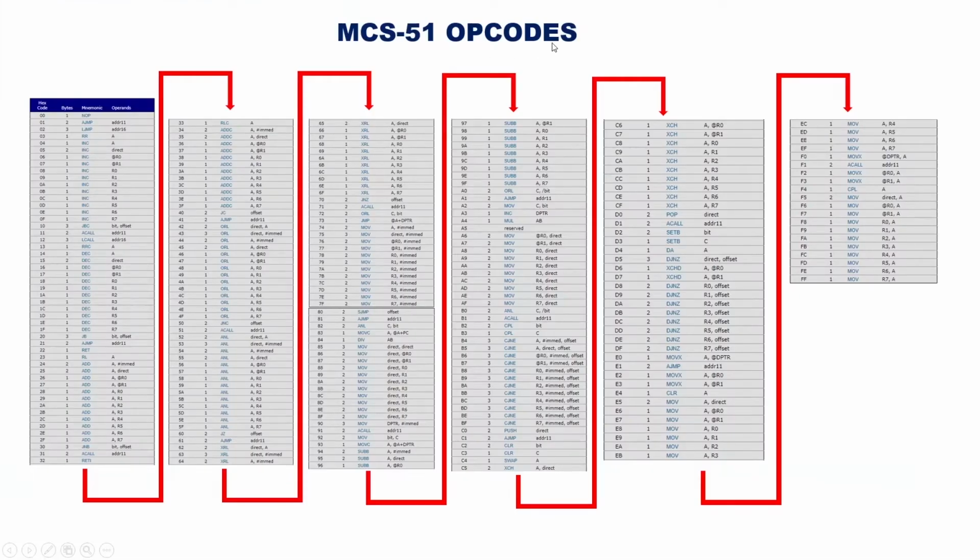In the MCS 51 of course we can find the instructions MOVX A,@R0 and MOVX A,@R1. Both of these instructions, MOVX A,@R0 and MOVX A,@R1, are used to move data externally when we use the microcontroller in microprocessor mode. But here we can find two other instructions, that is MOV A,@R0 and MOV A,@R1. These instructions are used to move data from the internal RAM to the accumulator, but only two registers from the register bank, that is R0 and R1, can be used for this instruction, that is MOV A,@R0 and MOV A,@R1.